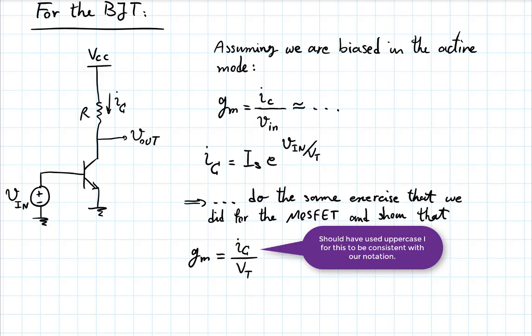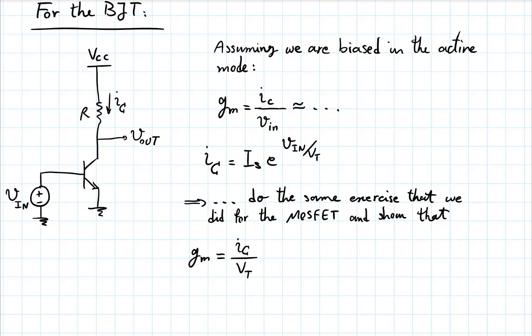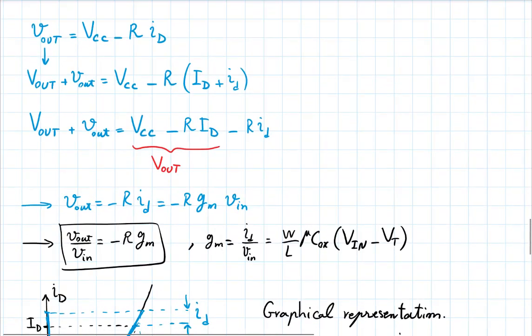And in fact, here's something fun. You see, if I want a high transconductance to get a high gain, look at this. The voltage gain was just that resistance times transconductance with a minus sign. If I want a high transconductance, I need a high bias current, right?